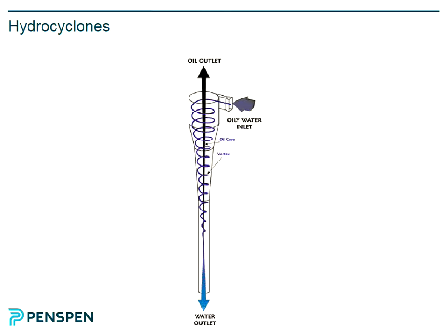You may be required to increase the gas pressure to export it to a sales pipeline, to use it as a product, or to use it as gas lift to increase the productivity of your oil in your gas lift system, or for dehydration and dew point control, or for re-injection into the reservoir.